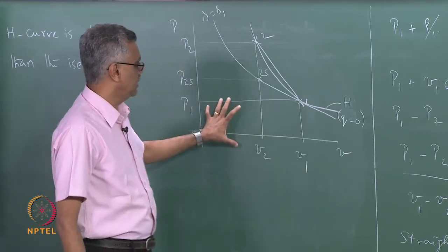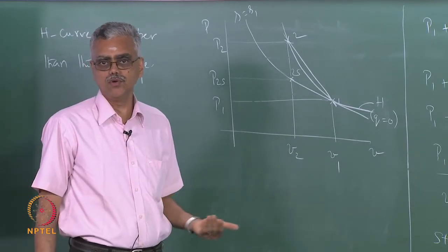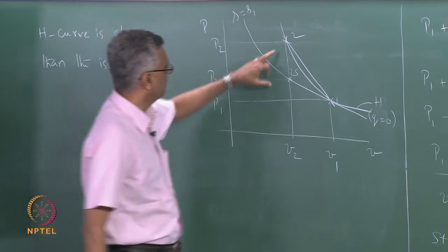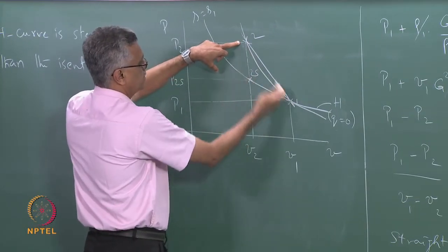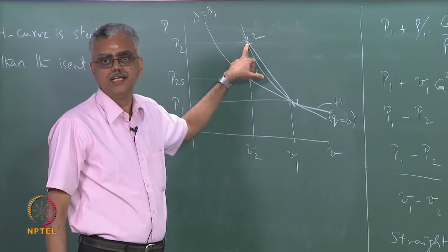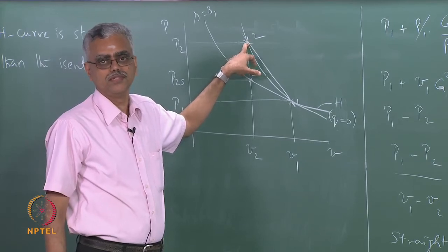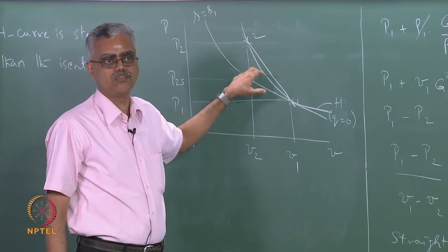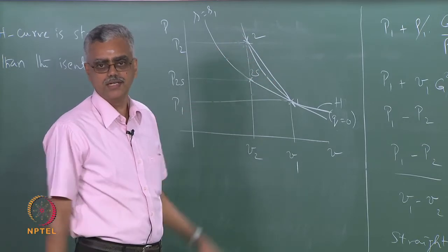Now this theory will be very useful when we go to the next chapter where we are going to look at flow with heat addition, especially this point about jumping from state 1 to state 2 without going through any of the intermediate states is very important, because if you have to go through the intermediate states, then you end up with a limiting condition called thermal choking, which is not there for the normal shock wave because it is a discontinuous solution. I can go from here to there, we will discuss that next.